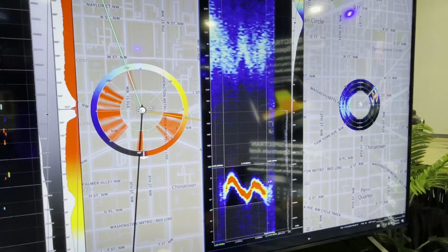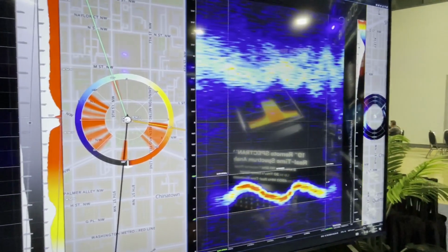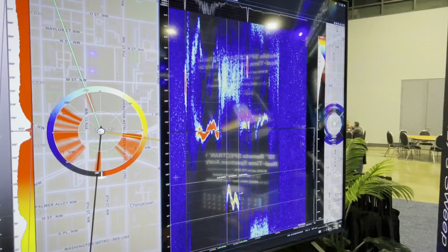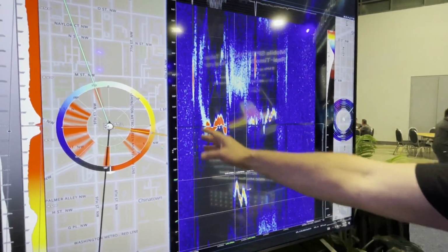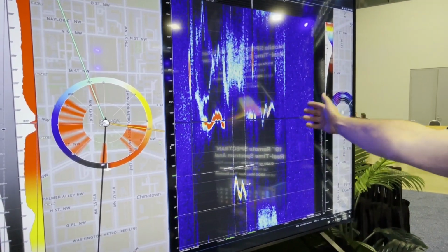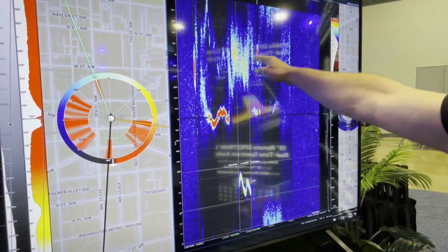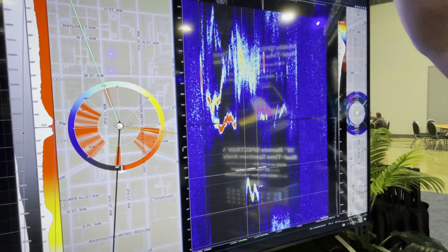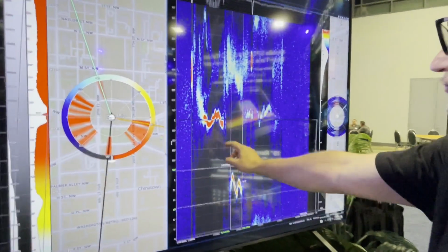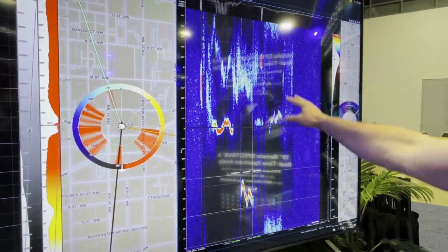And of course we can scale that a little bit more, and then you will see how it works. So this is the complete Wi-Fi band here. This noise here is all the transmissions from Bluetooth. And you can see that we have the routers installed somewhere in the ceilings, and they are very, very strong. And all the glitches you see are communications from the mobile phones.